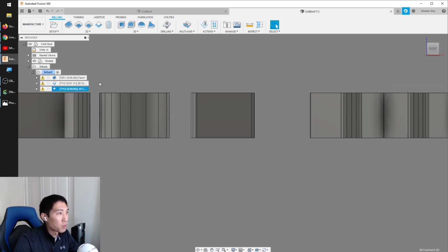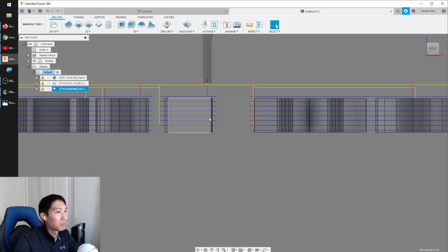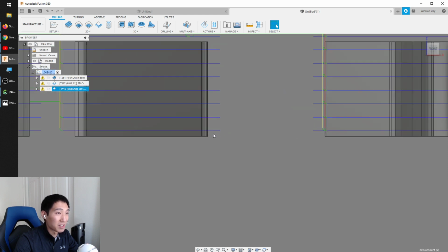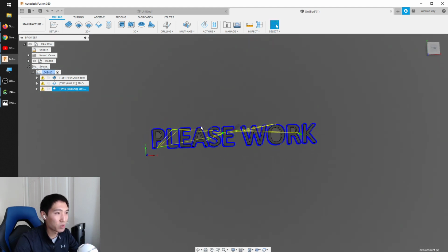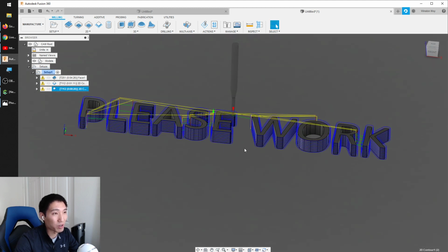And then my toolpaths will generate, and they will come down to right about here. And so you can see that this isn't going to cut all the way through the stock. You can cut a little deeper. You can play around with that onion skin, maybe make it 0.005 inches, and then just sand away the back and liberate all your letters. So there's a lot of different ways you can do this. Just given that these letters are all separate, I'd probably go with the onion skin.